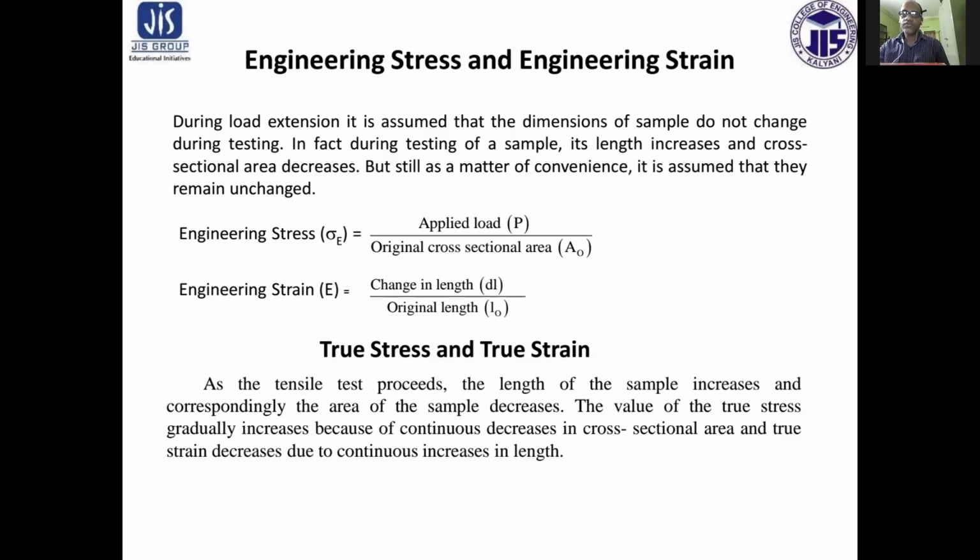First of all, we need to know what is engineering stress and engineering strain. During load extension, it is assumed that the dimensions of the sample do not change during testing. In fact, during testing, its length increases and cross-sectional area decreases. But as a matter of convenience, it is assumed that they remain unchanged.